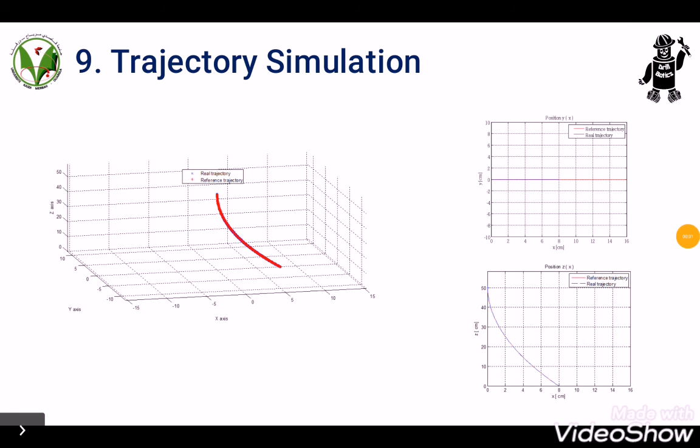These are the simulation results on a 2D and 3D plane the team has done on the theory of autonomous positioning. The method is based on the hypothesis that speed will be constant on the z-axis of the body frame, and developing the position expression along with the angle measurement with a recurring equation. In simple words, it uses the last and current position to determine the next position. Results on the 2D plane of the XZ axis were satisfactory and the theory seemed pretty applicable in the process of deviating by creating a perfect curve.